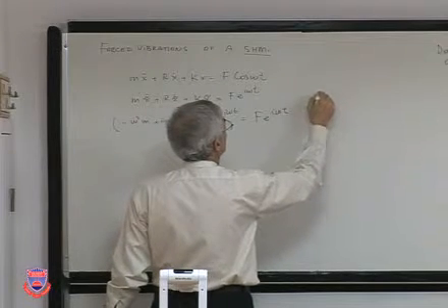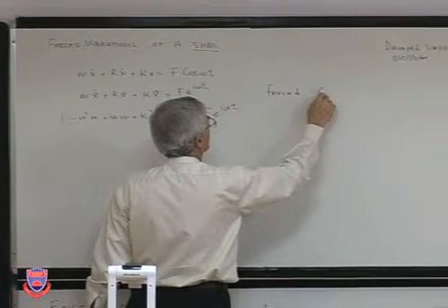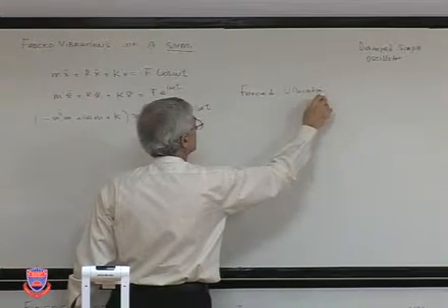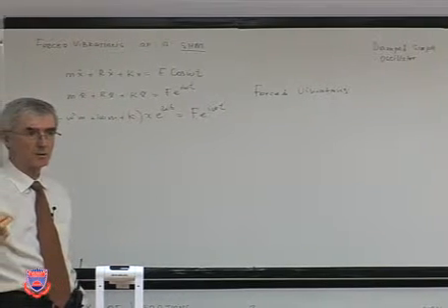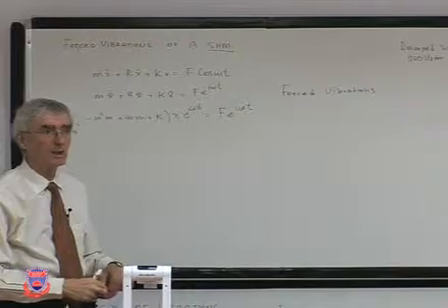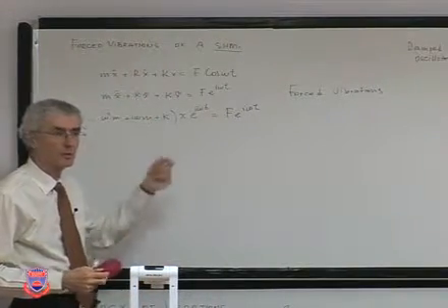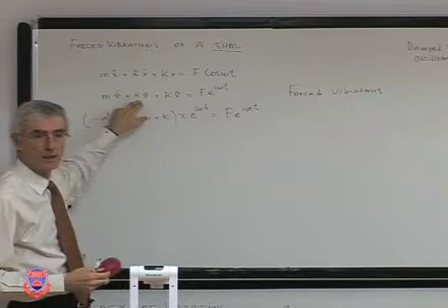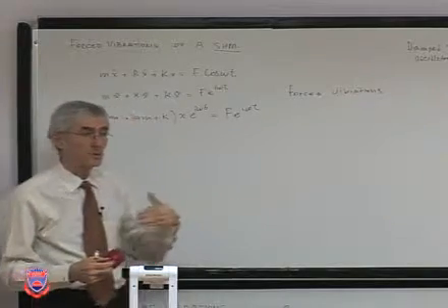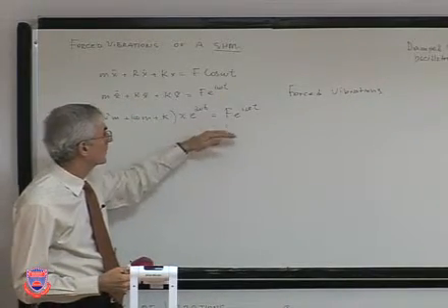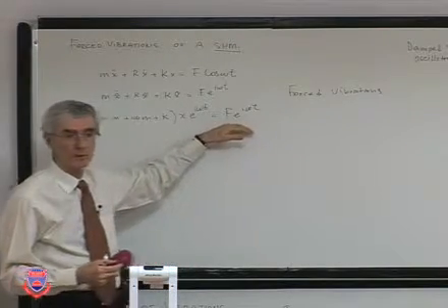Because it's a forced vibration problem. Technically, it has two solutions, a transient solution and a steady state solution. The transient solution is the one that's associated with its natural frequencies, but because there is damping in the system, it disappears in a very short time. So over the long time, it will be just the steady state vibrations, which must follow the force frequencies.